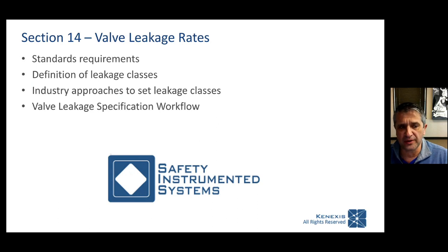The next thing we'll do is actually determine what leakage classes are appropriate. Once again, the easiest thing for an engineer to do, especially at an EPC company where you're just designing something for somebody else, handing them some paper, and then it's their problem, is to just say, well, everything needs to be tight shut off.